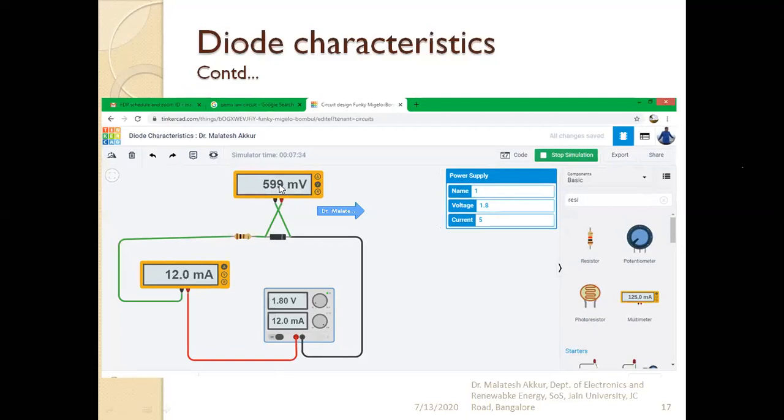So for a small change in the voltage across the diode, so not this applied voltage, this applied voltage is going to drop across this resistor as well as this diode. So as we know, when the diode is made forward biased, after the knee voltage, it starts conducting. So we know the knee voltage is 0.7 volts for silicon diode and 0.3 volt for germanium diode. Okay, the knee voltage, you can define it as the forward voltage across the diode at which it starts conducting. In a simple way, we say.